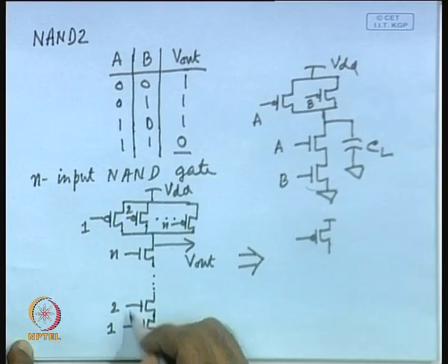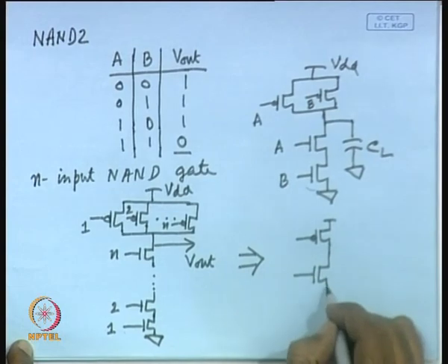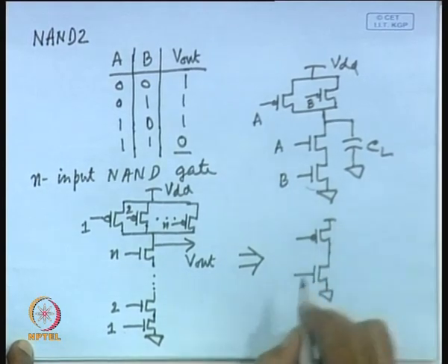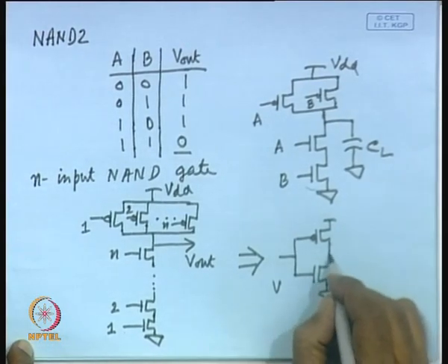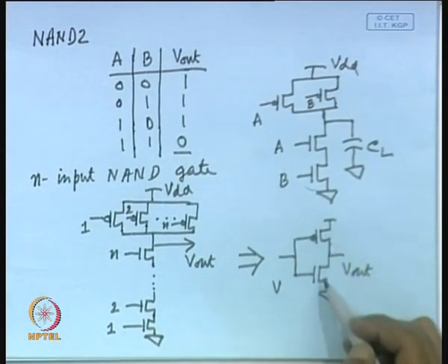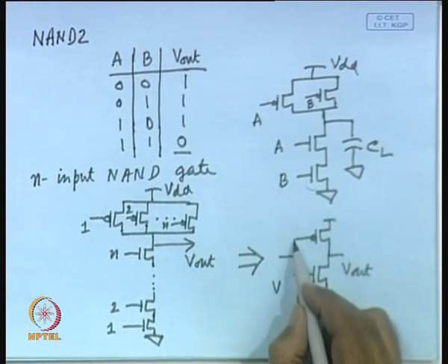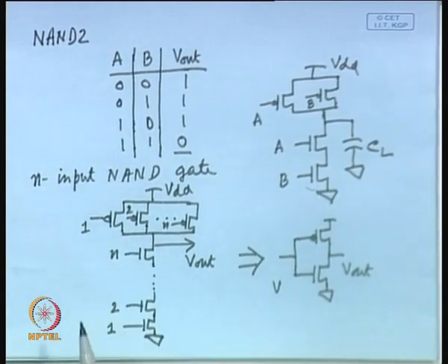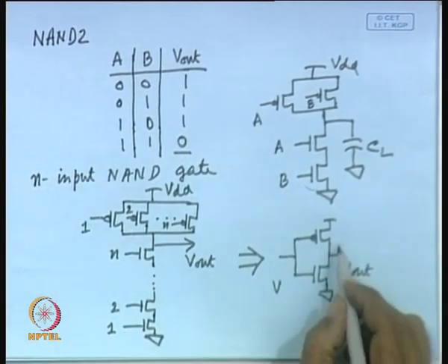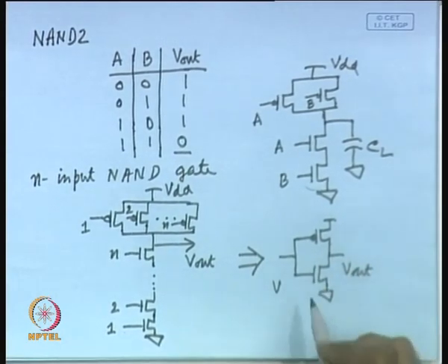Similarly, all the gates of the NMOS transistors are tied together, and it is represented by a single NMOS transistor, and then you connect it to V in, and here it produces V out. How the W by L ratio is changed when you convert it into a single inverter by tying all the inputs 1 to n together, and then it behaves as if it is an inverter.